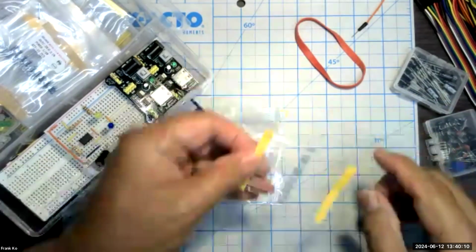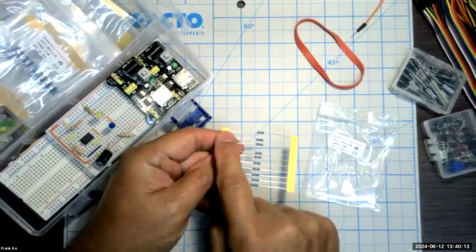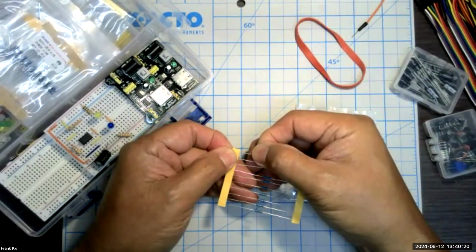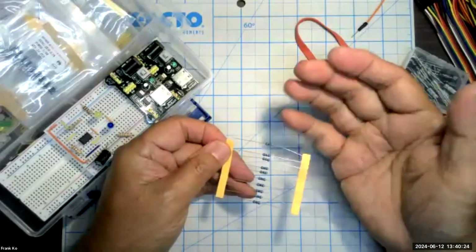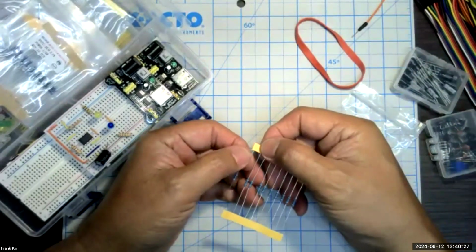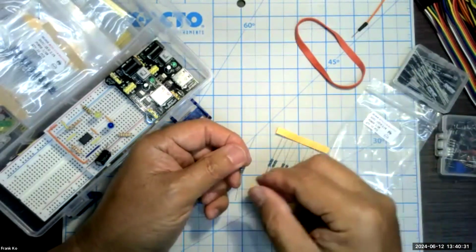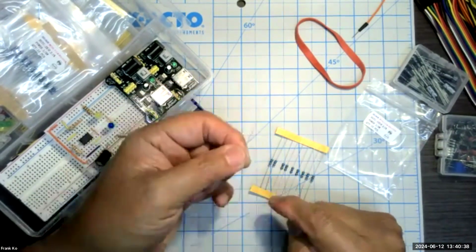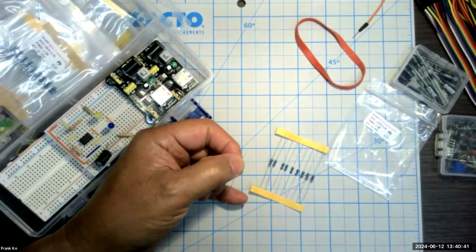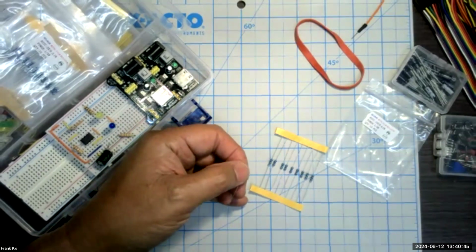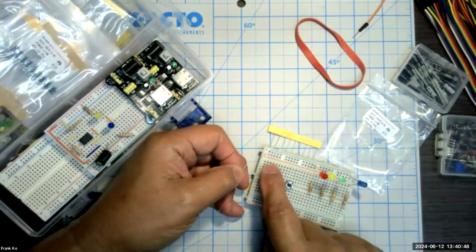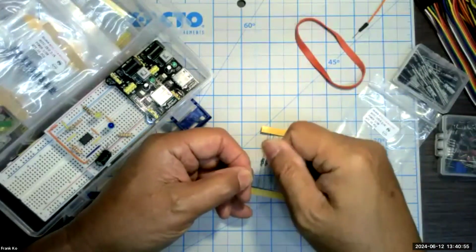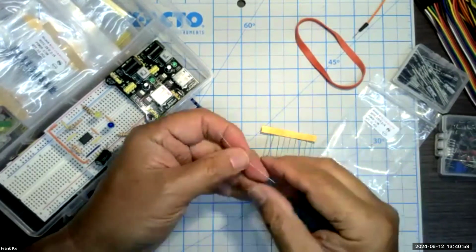So what you do here is, as these resistors are fastened with masking tape on either side, you want to very carefully hold the tape with one hand, and very carefully pull out one end to free that, like so. Then, very carefully on the other end, hold the masking tape and pull this out. All right. Now, the most common issue students have is there may be some masking tape residue still stuck onto the end of the resistor wires. The last thing you want to do is to have that adhesive go down into your breadboard and gum up your pinholes. So I highly recommend that your hands are clean, your hands are dry, and you can just very simply do this. Just remove any type of residue that's there.